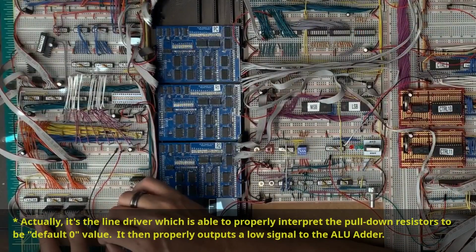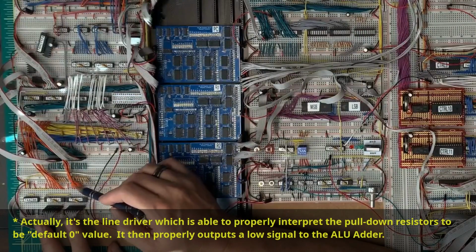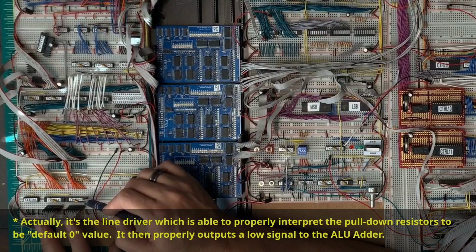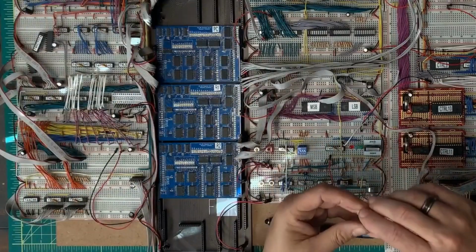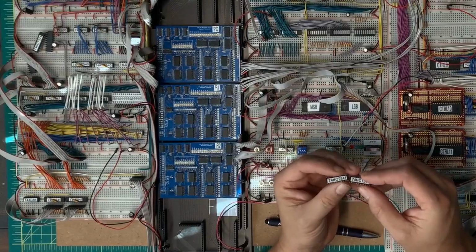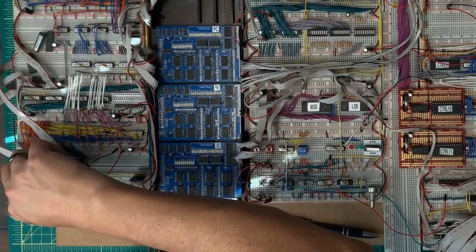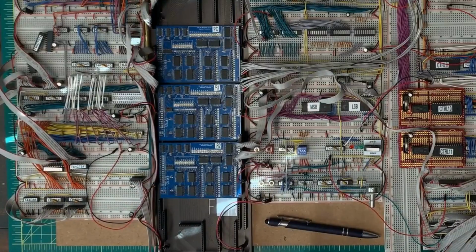The inputs here are going through a line driver. The line driver is actually able to pull that signal properly low. My plan is to take a look at this and add in 74HCT541 line drivers here and here, and have those permanently tied so that they're always outputting, so that the change is literally propagated through.